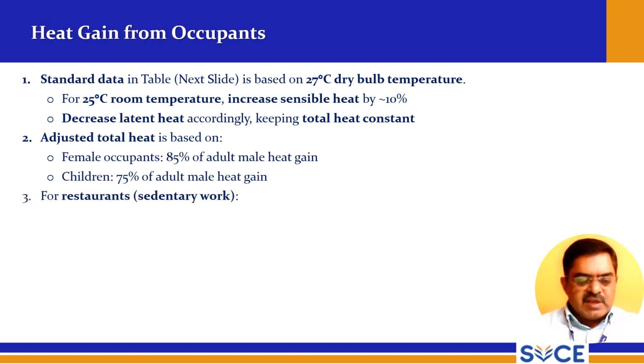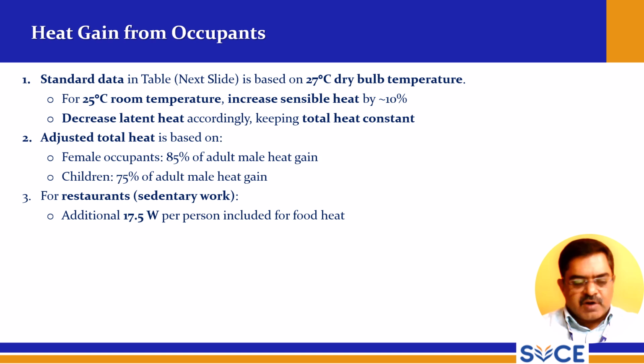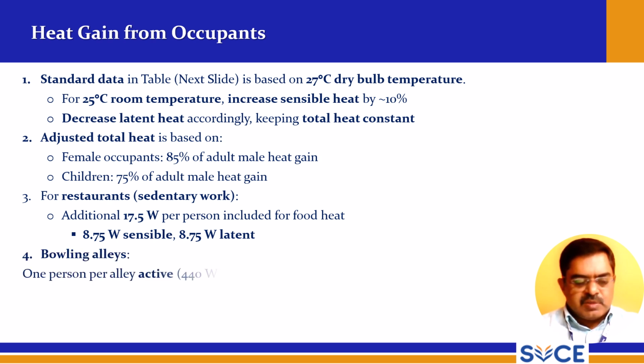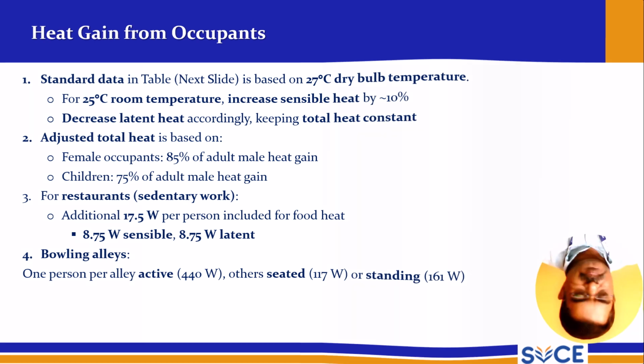For restaurants, sedentary work, you can see an additional 17.5 watt per person is included for food heat, 8.75 watt sensible and 8.75 watt latent. And for bowling alleys, with 1 person per alley active, it is 440 watts, and other seated is 117 watt or standing 161 watt.